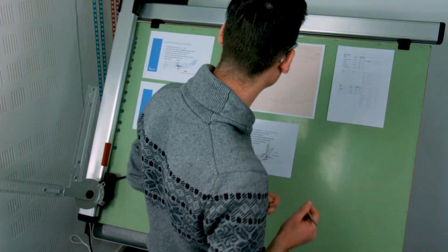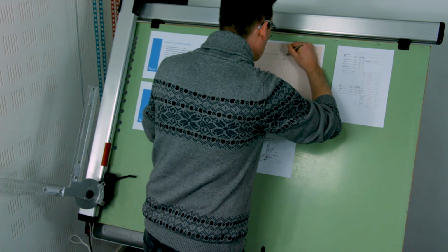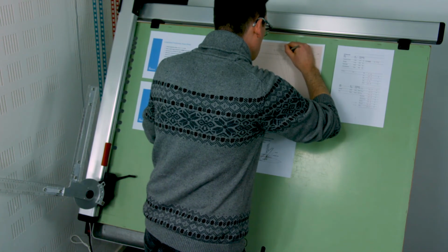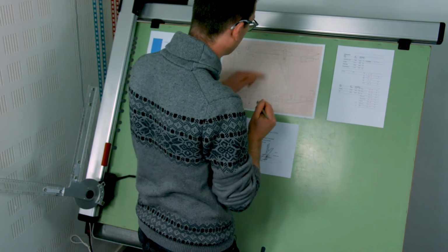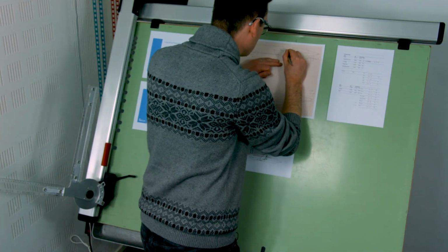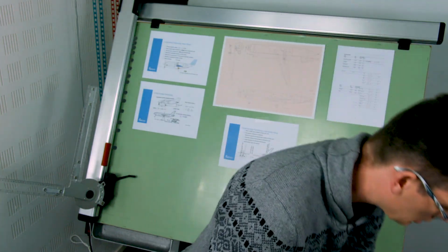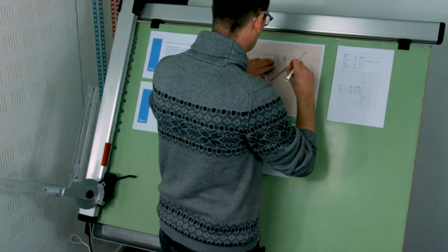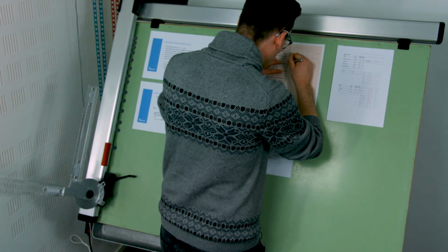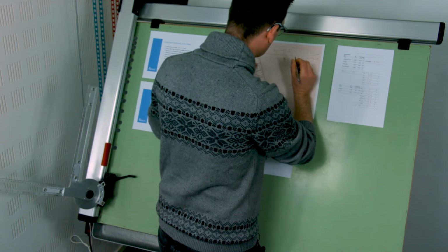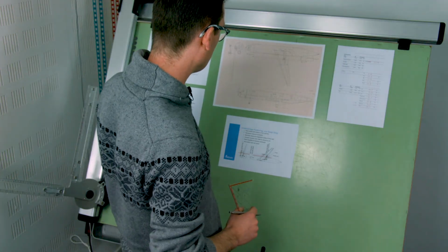the original trailing edge that I had, just to make sure that I convey the message that we actually have a kinked wing rather than a so-called straight tapered wing. So the undercarriage integration, particularly the main gear, has an impact on the wing planform, and I've shown that over here.